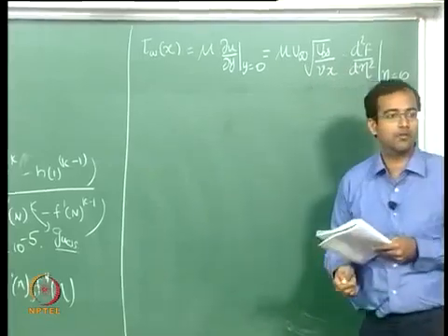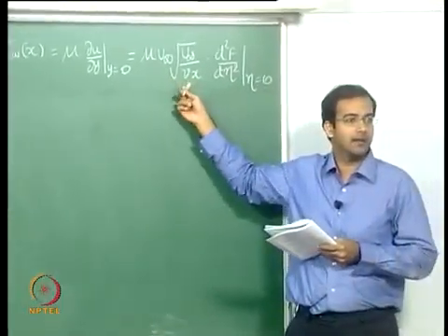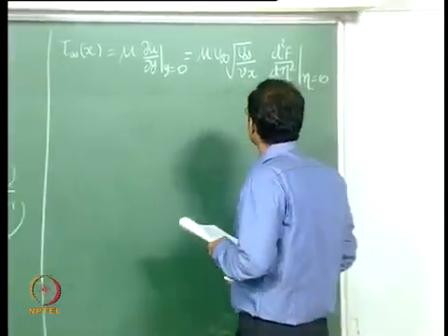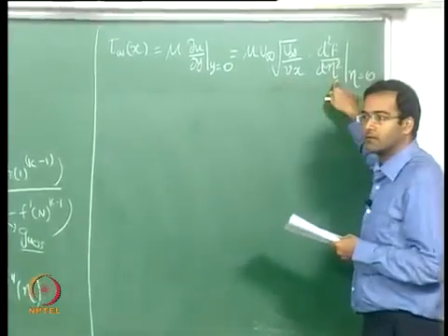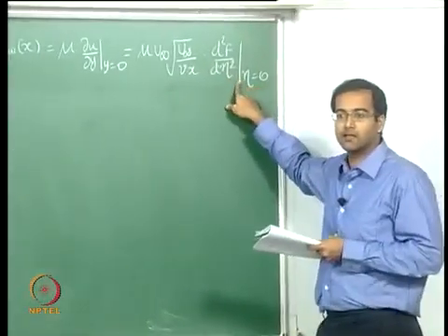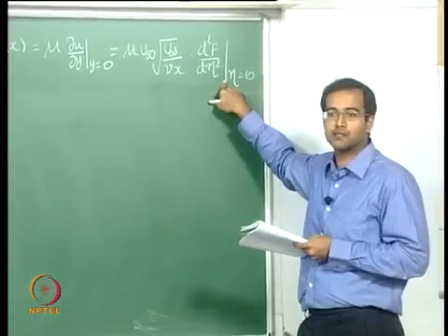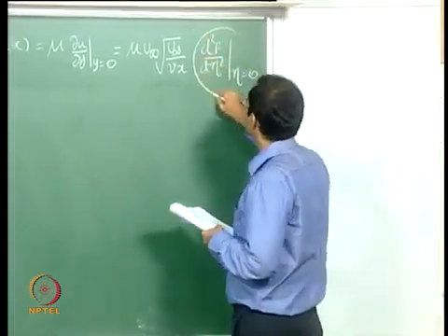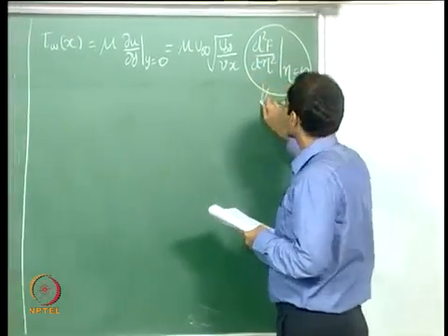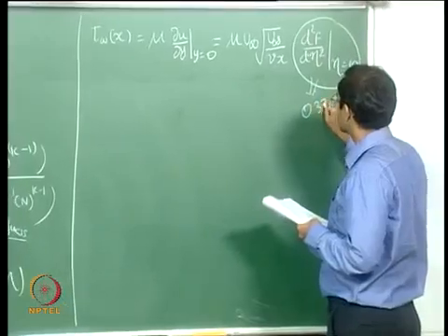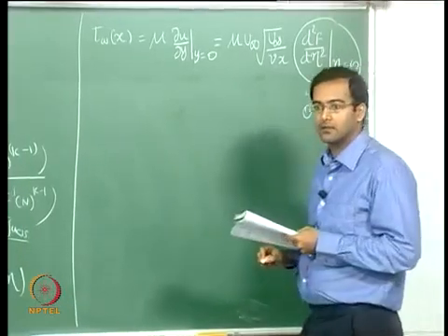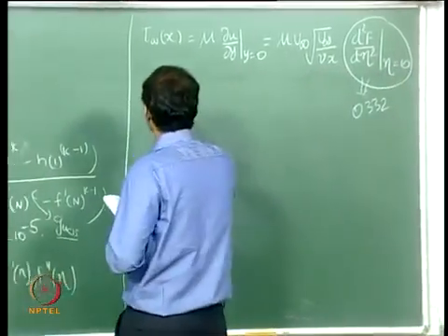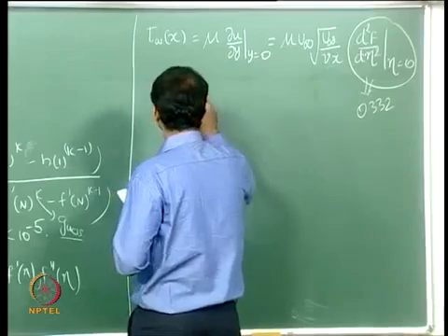Okay, I hope all of you have this. We have derived it. So now as he said, we have got this value either numerically or from the Blasius solution, that at eta equal to 0 the curvature is 0.332. Okay, so therefore your tau wall is